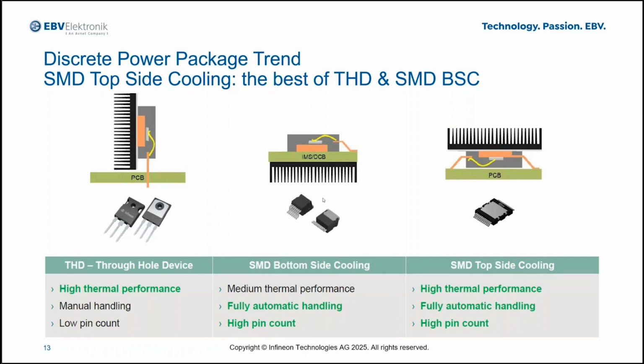On the contrary, SMD, typical D2PAK packages, which are very common for silicon carbide with 7 pins, are very familiar to whoever has designs in silicon carbide using discretes, but have a much more limited thermal performance. You would probably need an IMS substrate or a PCB with a lot of thermal vias, and the heatsink will not be directly connected to the devices.